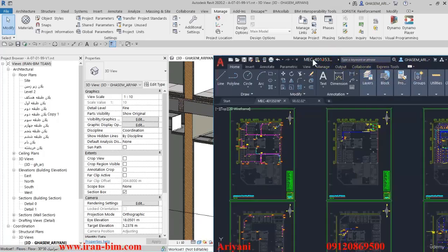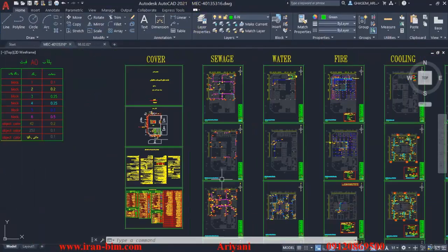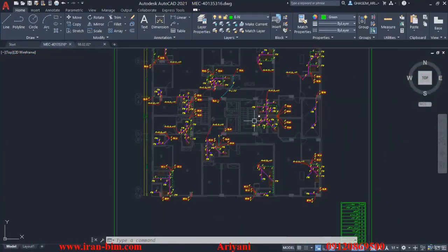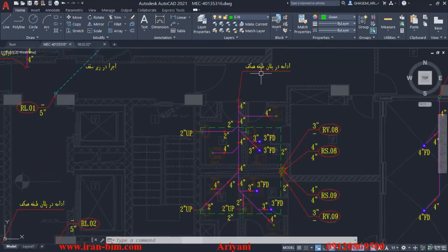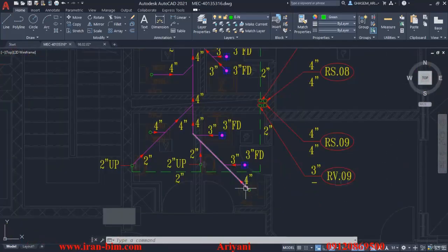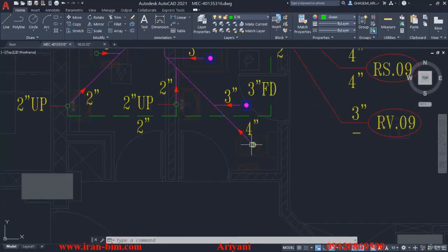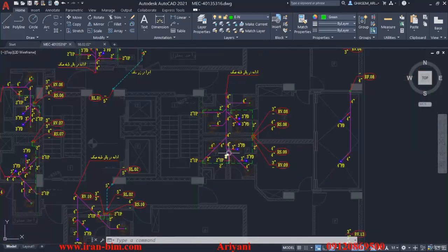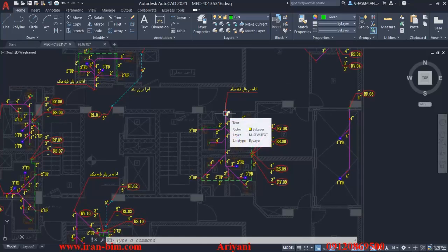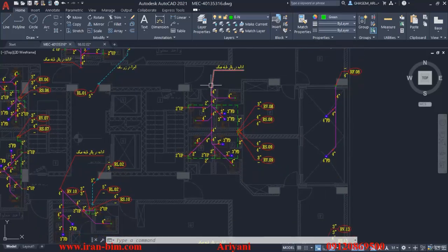So let me just go over here in the AutoCAD file and then go upstairs to show you the direction. For example, here we have a line right here and it says the rest is done in the ground floor. So this line goes from here and then through here, and it has to move with a 1% slope. The level that you see under the ceiling may be around 50 centimeters. And if it moves with a 1% slope, it may get to 60 centimeters. So this is moving with a slope, and we may not have collisions any earlier, but we will have some the higher that we go.